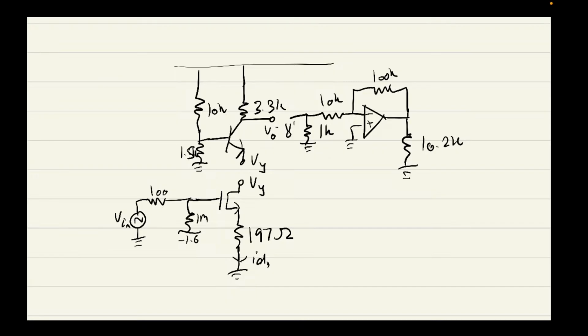Yeah, okay, so I'll quickly just state the gains for all of these. You get about 25.74 over here. No, that's over here. Minus 0.065. This is an inverting amplifier, so you get minus 10 over here. Total gain's about 17.64. That makes your closed loop gain about 13. Yeah, I'm sorry we couldn't complete this question. We've run out of time, unfortunately.